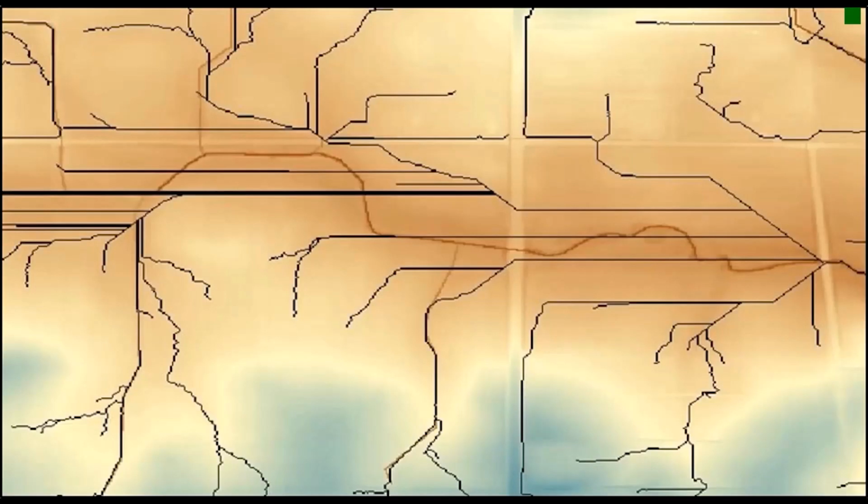If no cut or dam lines are made, there's a good chance your flow paths are going to be inaccurate. This example shows a DEM where the flow path should be along the dark brown line. Because no edits were made, the actual flow network that we get, shown in black, is just skating across the landscape, which is not realistic or accurate.